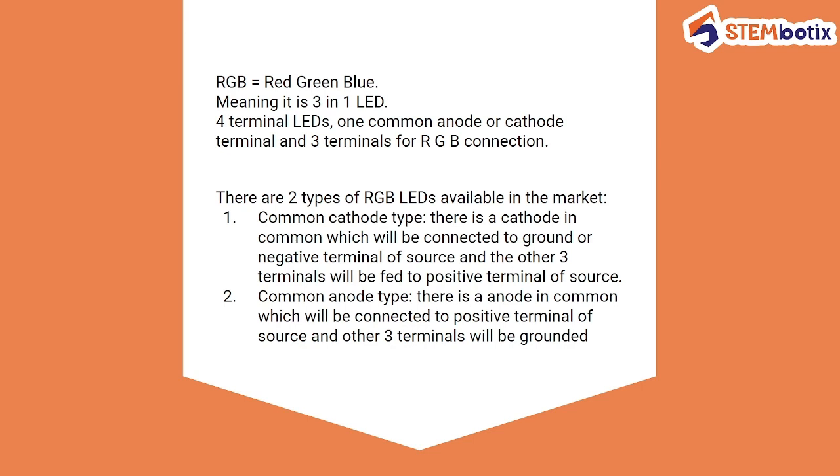So at a time you can turn on either red or green or blue light from a single LED, meaning it is a 3-in-1 LED. It is a 4-terminal LED. It has 4 terminals, one common anode or common cathode depending upon the module you are using, and 3 terminals for R, G and B connection.